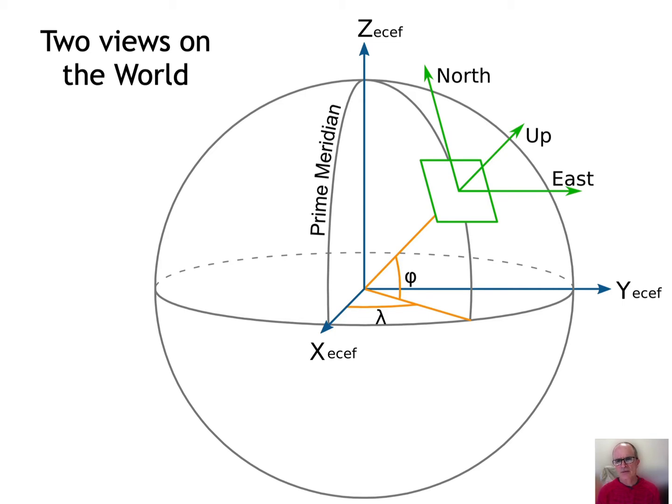From southern to northern Minnesota, if you tried to use one flat surface for the whole state, you would get tens of feet of error in measurement, so you'd mislocate things. And depending upon where you started and how you did your measurements, things wouldn't line up correctly. So we have to somehow render the curved surface onto a flat surface, and that's the second part. In the next lecture, you would do that in map projections.